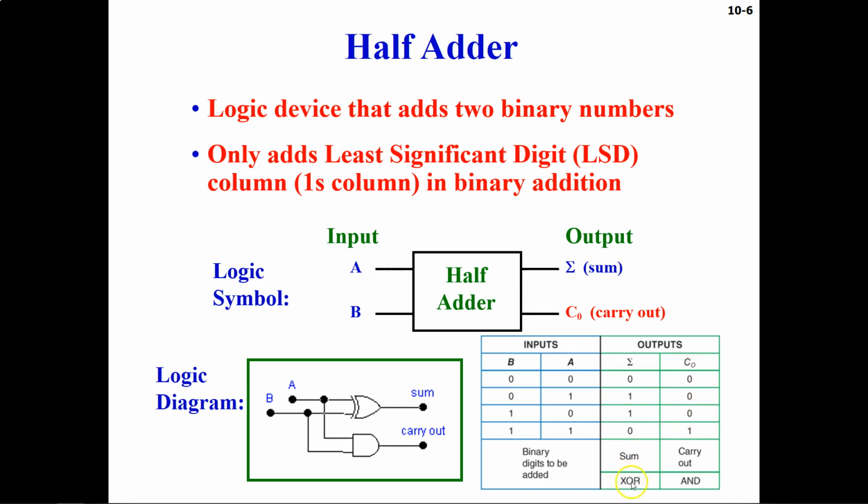And for sum you have an XOR gate, and for carry out you use the AND gate. And you can figure this out from this expression also. So wherever you have ones, look for that. So we have 1 here, and corresponding to this, we have B bar A. Then we have another 1 here, which has B and A bar.